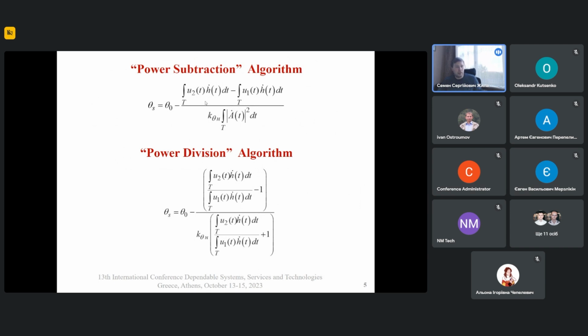So in this case, we have every signal from our antenna in the receiver, taking into account internal noise, which has to be convoluted with the optimal pulse characteristics of the receiver, and this pulse characteristics is defined by the envelope of the signal and central frequency. Then we have to calculate the subtraction of these powers, and this subtraction has to be divided into k.